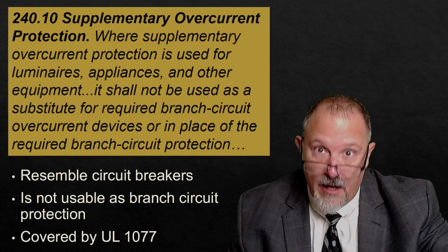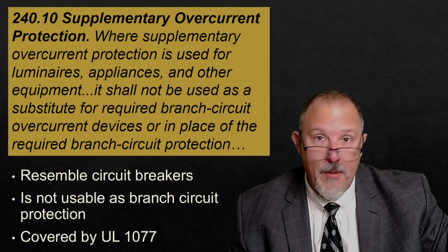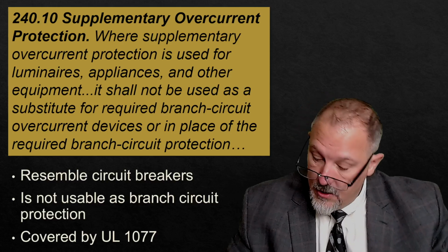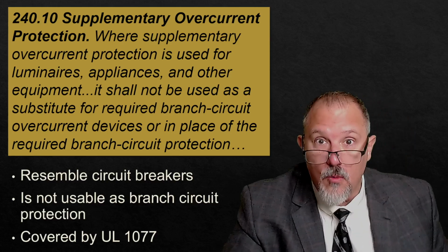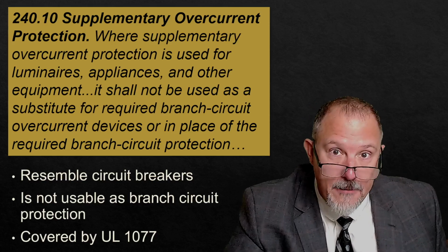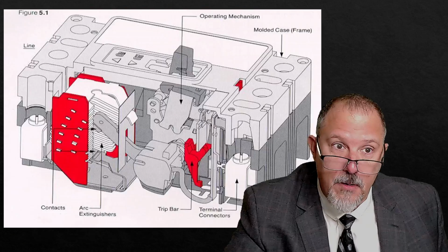They do look like a regular circuit breaker. And if it was a fuse, they look like a regular fuse, but they are not listed that way. So you've got to make sure, and this is why we look at listings. This is why we require listings. This is why it's important that we understand the proper application of products in the field.